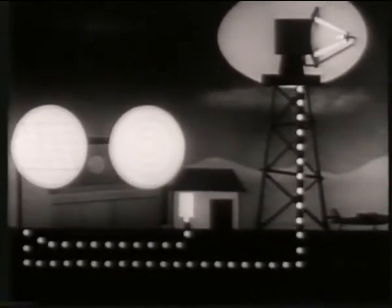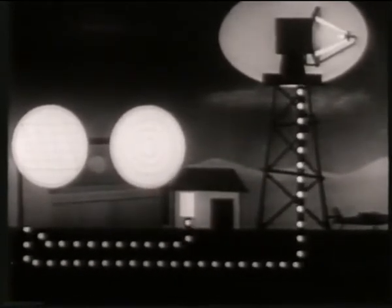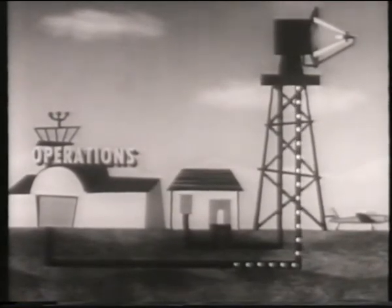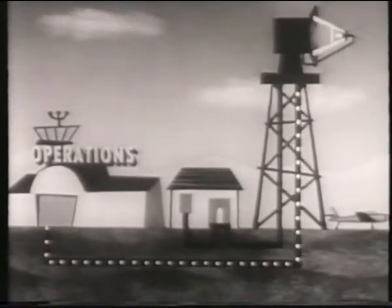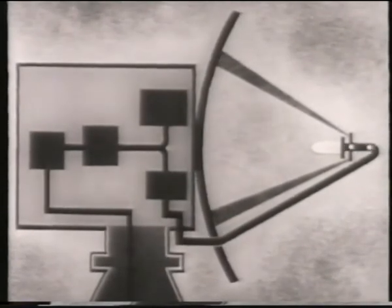A radar system has 5 main parts: a radio transmitter, an antenna system, a receiver, a control system, and a display unit with a viewing screen. The transmitter generates radio frequency energy in short bursts or pulses. These radio pulses go to an antenna system, which sends them out into space in a highly concentrated, narrow beam. If some of the pulses strike an object, they rebound, and some of their reflected radio frequency energy is returned to the antenna system.